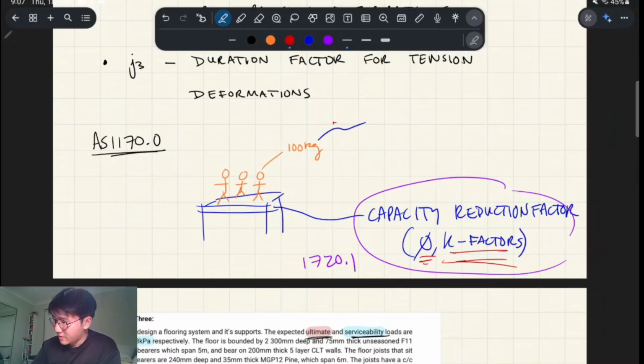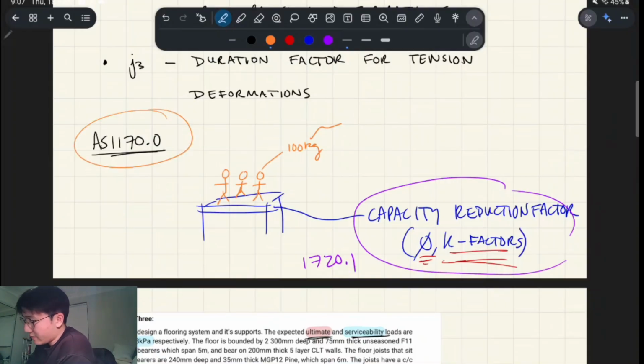Now, just from a loading perspective, because this isn't exclusive to timber, this isn't exclusive to steel or concrete, this is just loads in general, you have to exaggerate the loads. You have to pretend that these tradies, instead of being 100 kilos, are, I don't know, 120 kilos or something, worst case scenario. And so in our load combinations code, we have exaggeration factors basically.